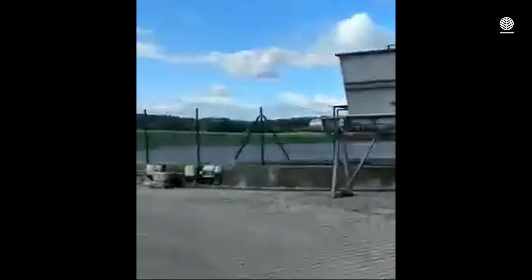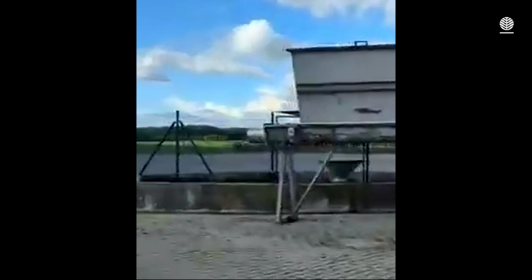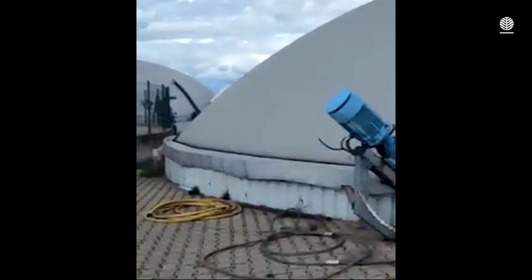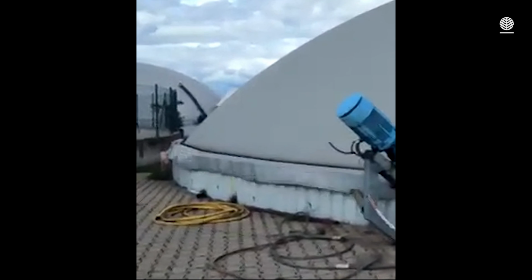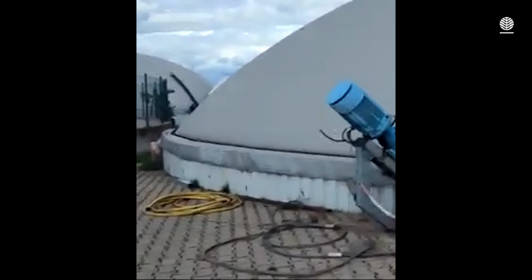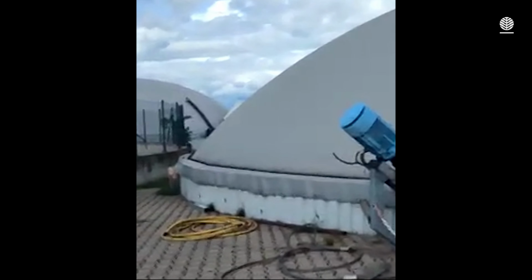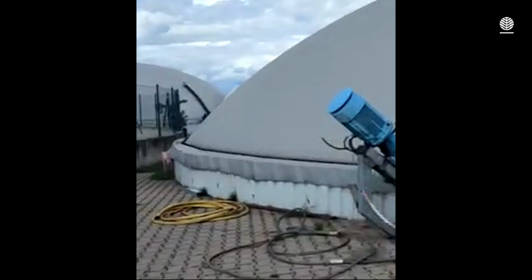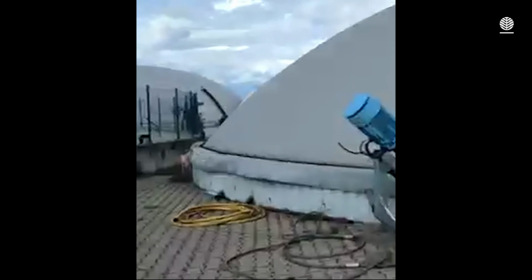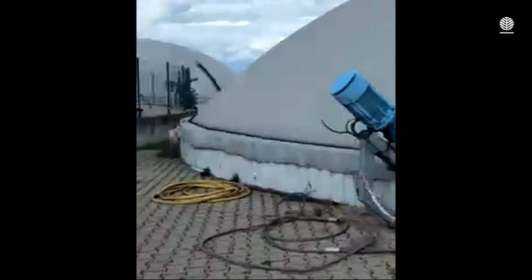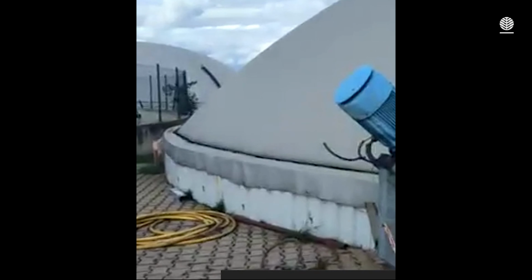This is an agitator. You can see on the right side, the blue one. This is a propeller, not submersible. It's a propeller mixer, and we use it here because it's all dewatered. There's no fibers inside. Everything we store inside this digester is dewatered before. It's very important to avoid floating parts, scum, and sediments.